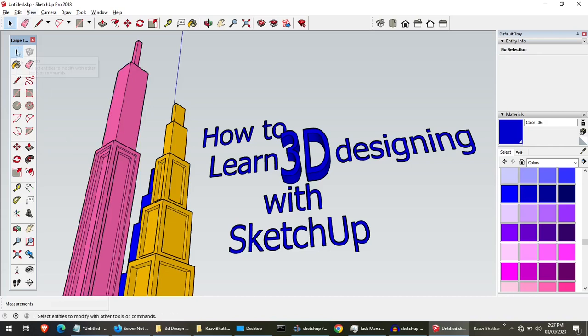So now you have learned to use the select tool, the paint bucket tool, the rectangle tool, the push pull tool, and the move tool for moving objects. And you have also learned to use the offset tool and the scale tool. Some of the tools are remaining, which we will cover in another tutorial. And one important thing which has remained is how we created this text. We created this text using this 3D text tool. So in the next tutorial, we will specially focus on how to create 3D text.